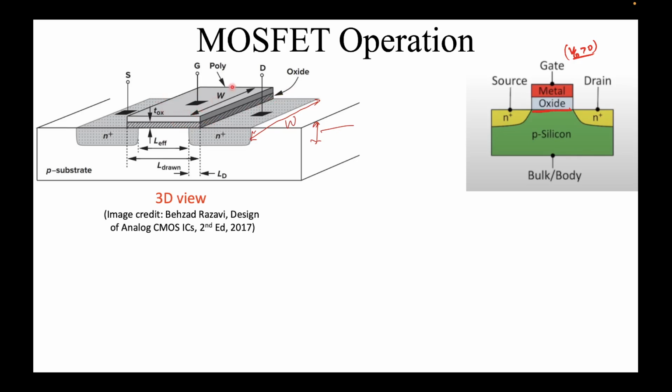And finally what we have is the metal. So you see this gate metal, which is over here, in the gray region. So this is the gate metal. So now we have the 4 terminals you can see: gate, source and drain, and source and drain are N plus types, just like this. And this is the P-type substrate. The other key thing to notice is the width of the device, W. Till this point, even in the case of MOS capacitor, we had never talked about this W. Essentially, the higher the width, everything else remaining constant, the current increases.